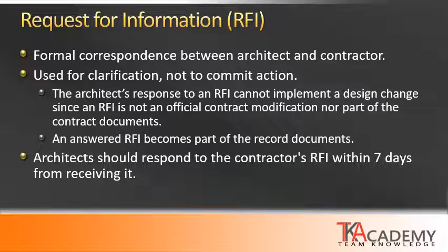One of the more common documents used during construction is the RFI, the Request for Information. This is simply the formal correspondence between the architect and the contractor. It is used for clarification, not to commit action. So if the contractor has a question of what is intended, what was meant by the contract documents, the architect's response should be to clarify that.